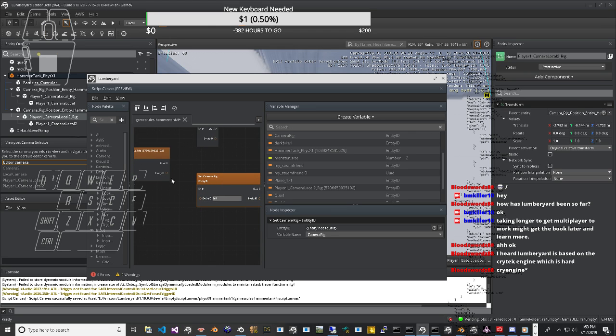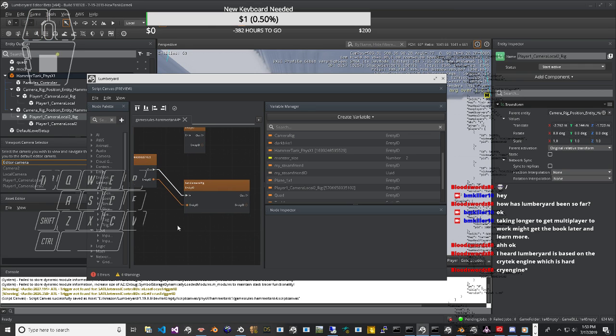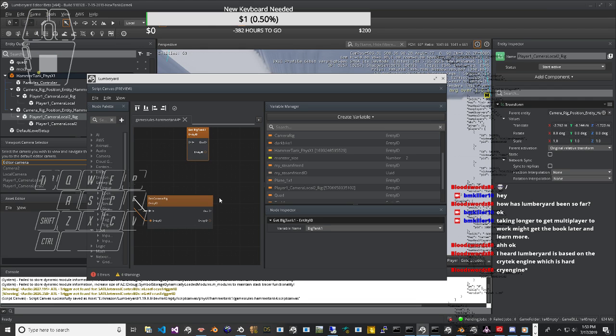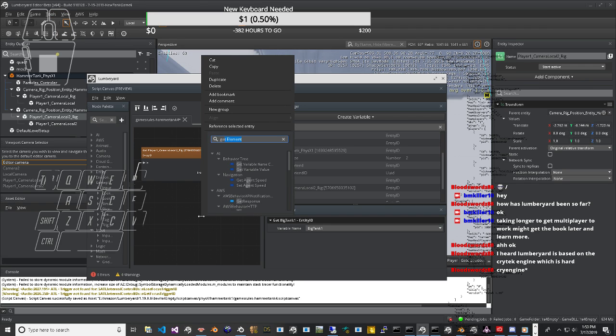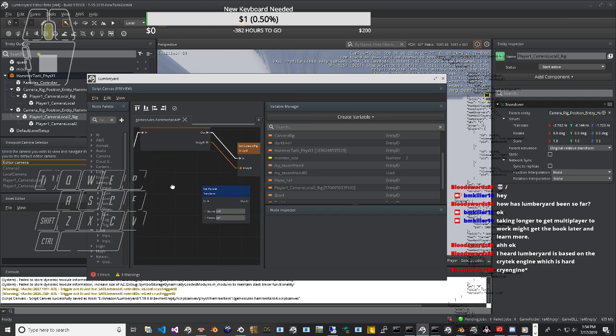The next set of coordinate frames is ROAD i, where i varies from 1 to 4. There are 4 frames representing the road under each wheel, numbered as 1 equals left front, 2 equals right front, 3 equals left rear, 4 equals right rear. Each ROAD i is located at the force center of its corresponding contact patch at the point Ri equals Rix, Riy, Riz, with respect to Earth.